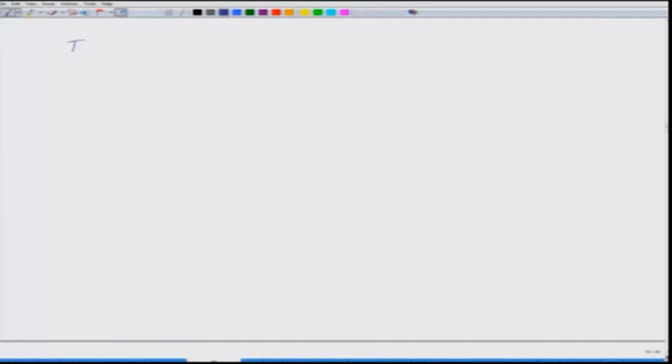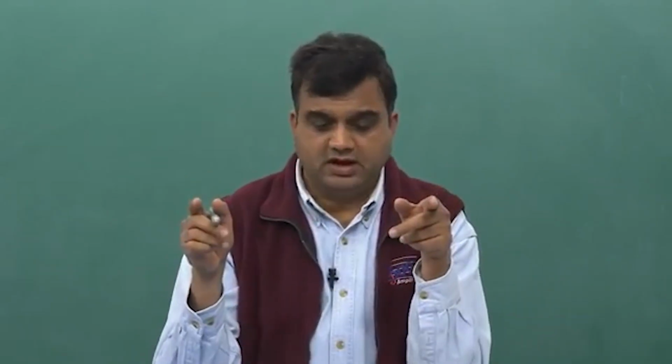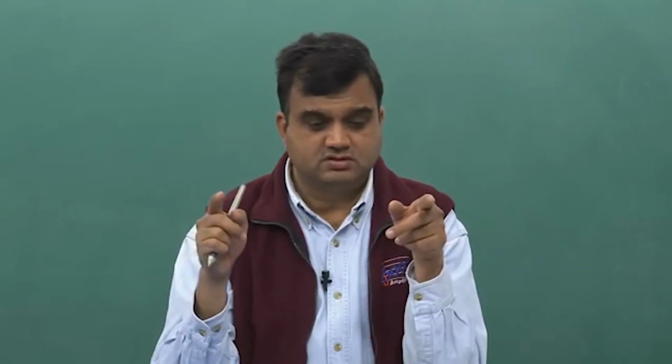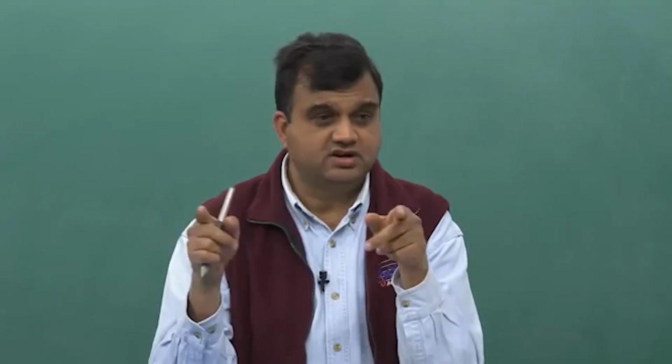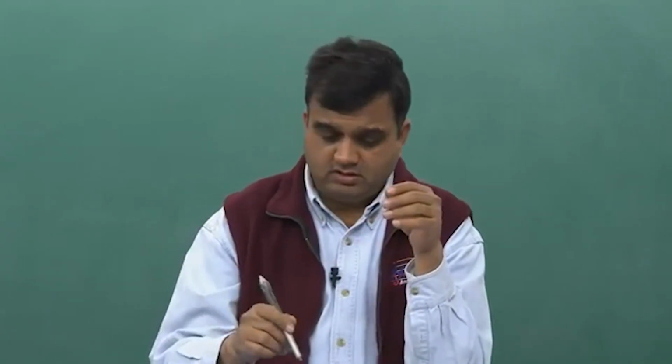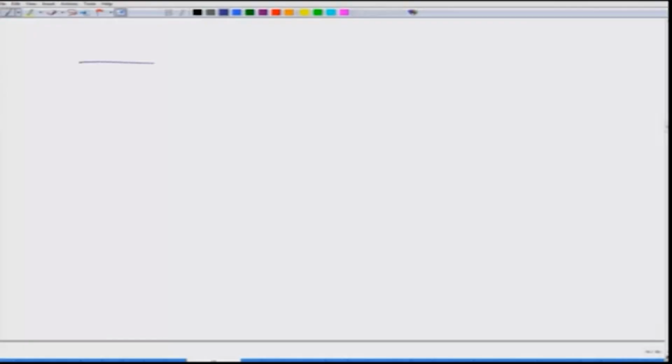We had said that if I break the domain, that is the region of our interest, which is from r equal to rI to r equal to rO, inside radius to outside radius, if I break that domain, so that is my domain, RI, and this is RO, and I break it into several elements such that this is my first element, second, third, and that is the nth element, and the size of each element is H1, H2, H3, Hn.